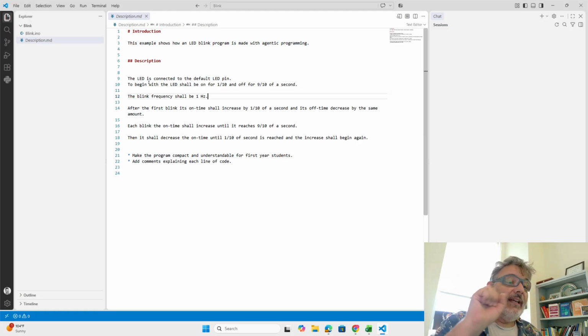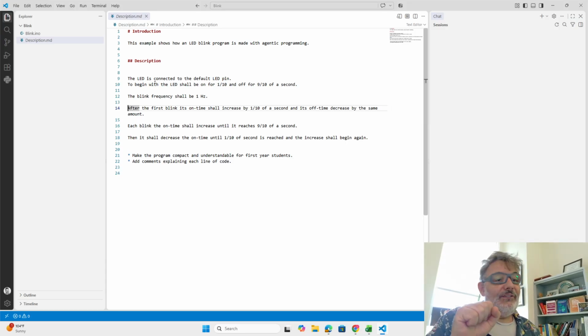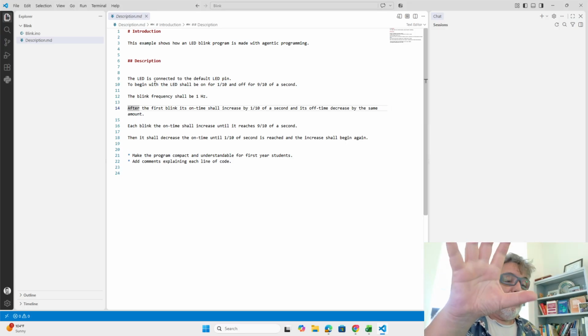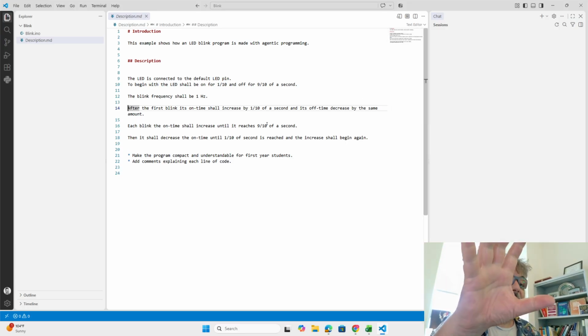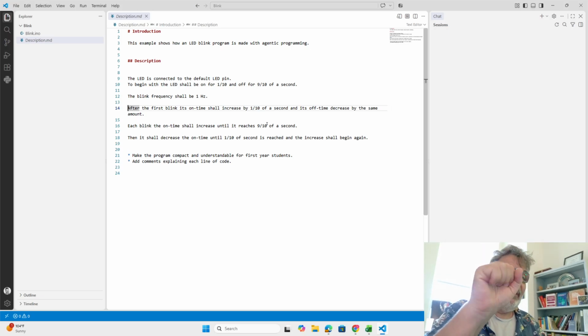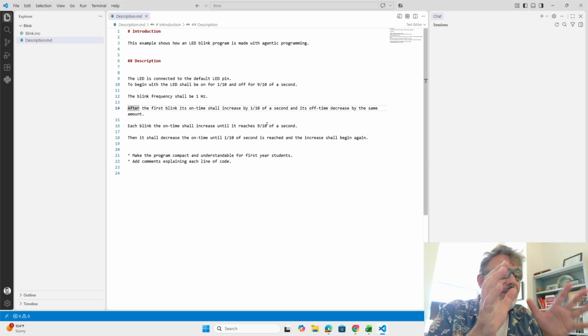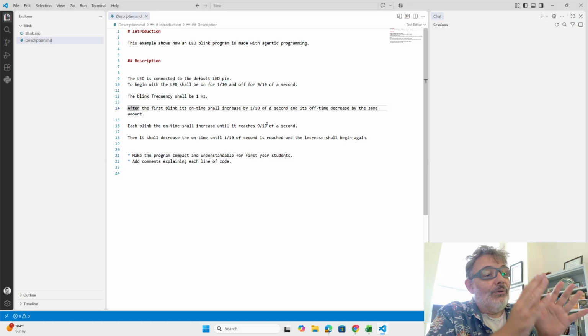So I still want to blink every 1 second. So this is 1 hertz, 1 blinking per second. Once per second is 1 hertz. And after the first blink, I say, we just said 1/10 on. Now I want it 2/10 on. The third time, I want it 3/10 on. The fourth time, 4/10 on. I want it on longer and longer. And then once it's on for like 9/10 of a second, I want it to become 8, 7, 6, 5, 4, 3, and get faster and faster, like so that the LED is going to be on shorter and shorter.